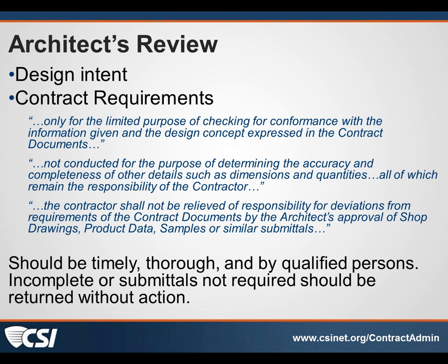I'm sorry, Jim. One other thing I would mention regarding submittals is the documents also allow us to hold a submittal if its review is dependent or contingent upon another submittal. So remember that too. A lot of times you've got an interface between curtain wall and masonry, or curtain wall and metal panel, and you need to see how the two are going together. And you've got the metal panel guy's stuff, but you don't have the curtain wall guy's stuff, and you don't know how the two are going to come together.